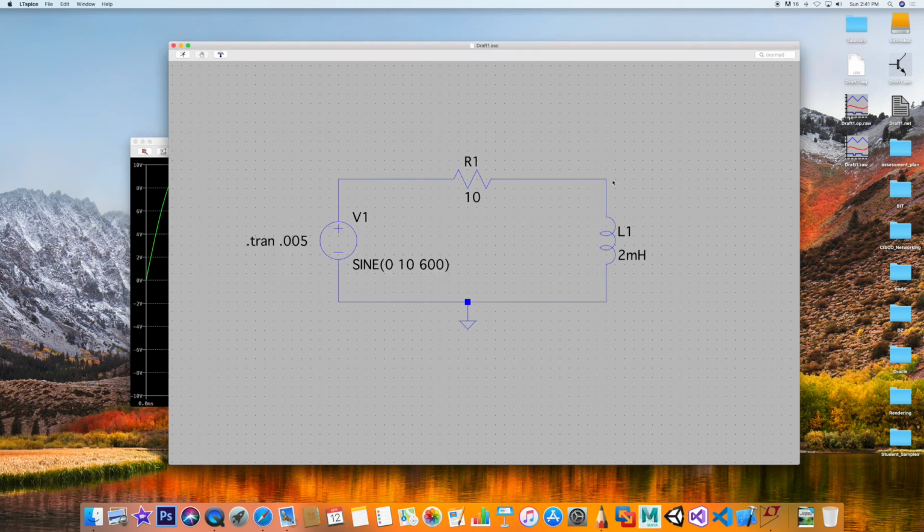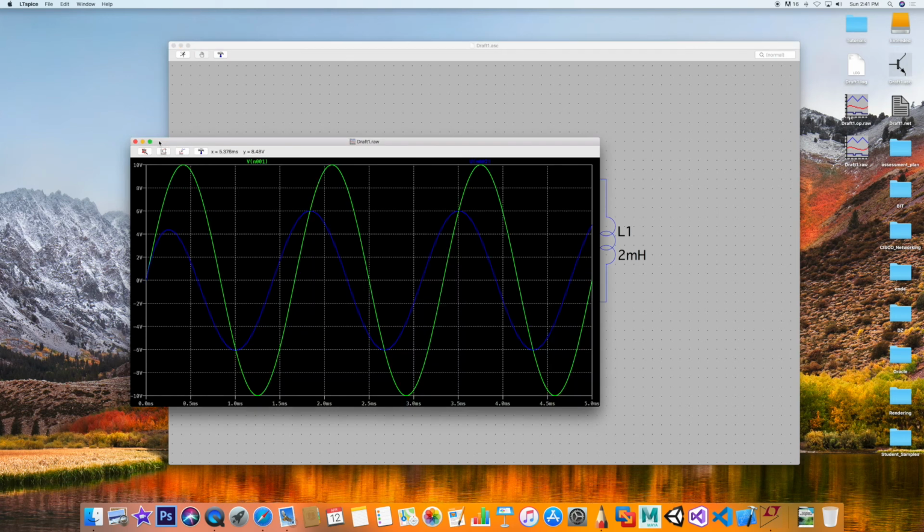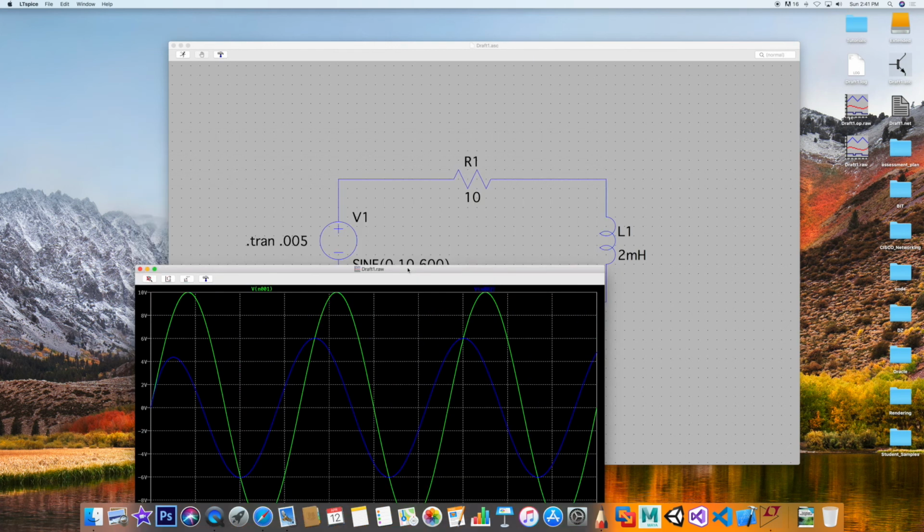Now let's compare it to the inductor. And let's try to understand the behavior of what we're looking at. And as you can see, at 600 hertz, what happened to the inductor's voltage? Now, notice initially, this is plain physics. It hasn't stabilized yet. It hasn't reached a point where it will stay at its steady state of almost 6 volts. So V sub L is 6 volts now, which means I have less voltage drop against the resistor. Right? Because the resistor is taking up the slack, the difference between the two.